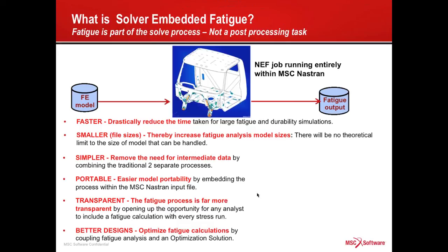You have one process, one stress calculation, or actually it's sometimes not even necessary to calculate the stress result, one fatigue calculation at the same time, only keeping the fatigue result and only outputting that into the output file. By doing this, we can dramatically increase the speed of calculation. We've got various estimates for this at the moment, but I'll mention later on an example where we think there is probably a fundamental increase in speed of about a factor 5 or 6.